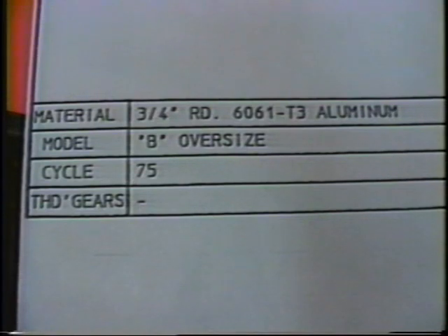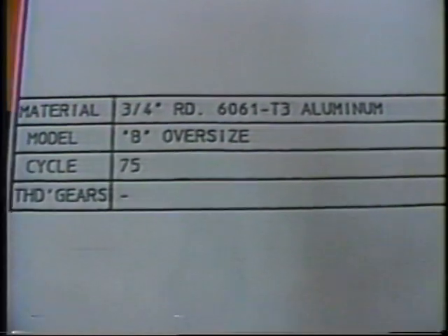If the production process requires the use of the threading clutch, the gear set will be identified numerically by the number of teeth on the driver, followed by the driven gear. This will be followed by the threading method to be used. Further information on available threading methods is found in the instruction book.